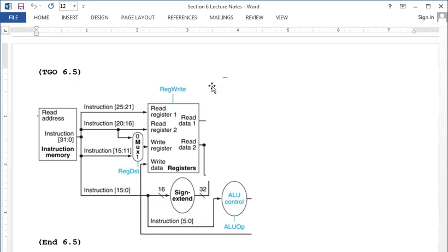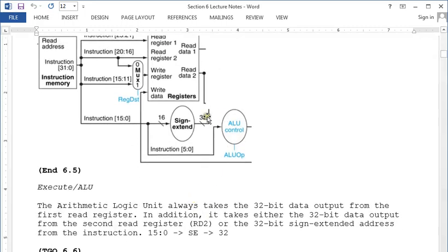If I shift left by 2, I'm multiplying by 4, because it's a word. Think, what type of addressing does MIPS have? Bingo, we have byte addressing. So we're going to be shifting this value by 2 after it fans out to the multiplexer.